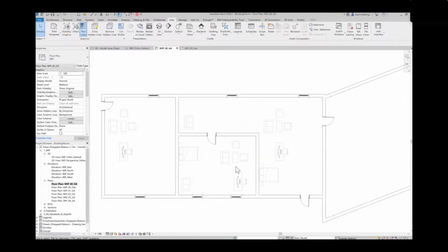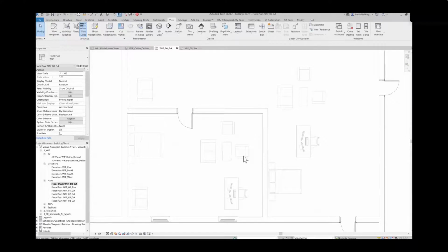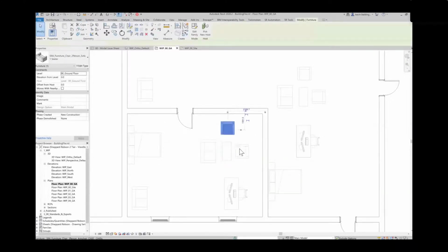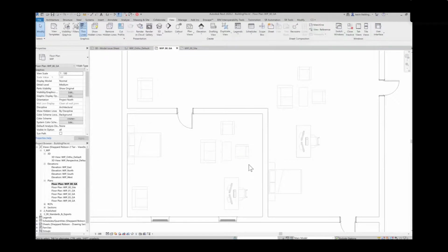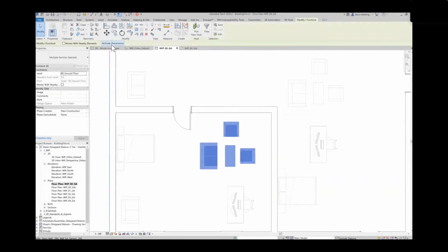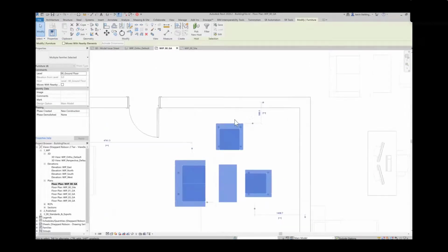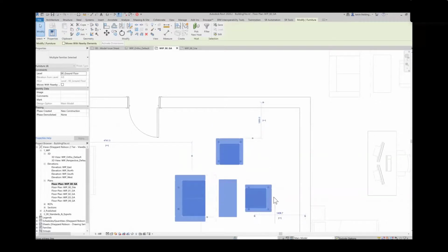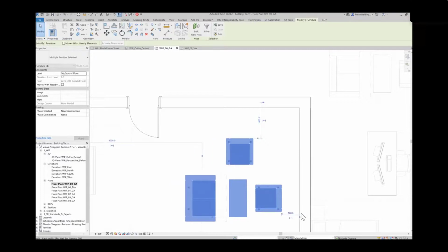This tip is how to accurately move geometry inside Revit. So we've got an example where we've got multiple groups of objects here. We want to move them all together. Now if you select them, you don't get any dimensions, but if you come up to your options bar and click on activate dimensions, you get the temporary dimensions. You can move these around, and you can then use these to accurately place geometry. You just have to remember to move the witness lines, and then you get some decent control of where you want this geometry to be.